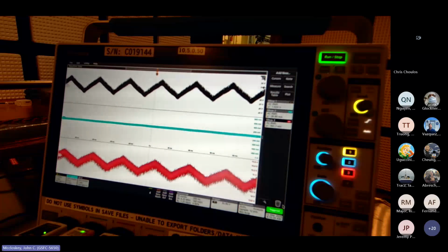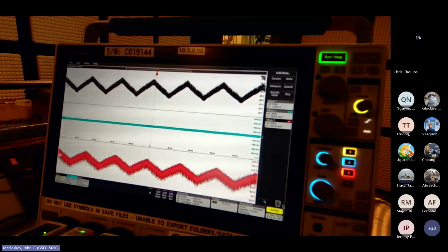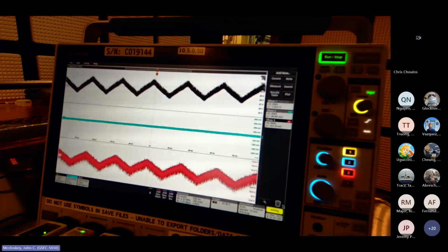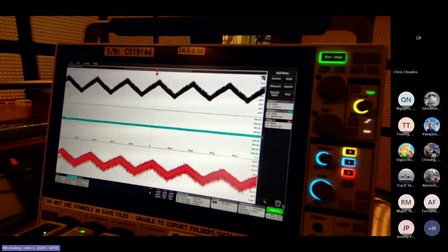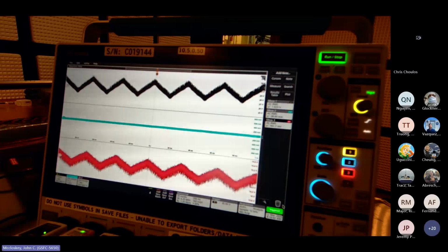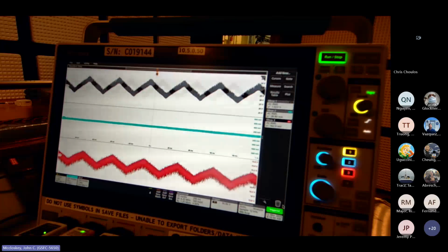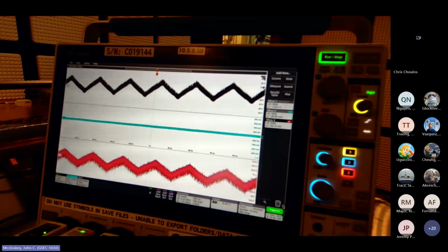Pre-calibration is an extra safety precaution. There's definitely nothing wrong with doing that. It's additional time, but I highly recommend the direct current monitoring method if you've got that capability in your control loop, and that is how we have been doing it at Goddard for a number of years now.